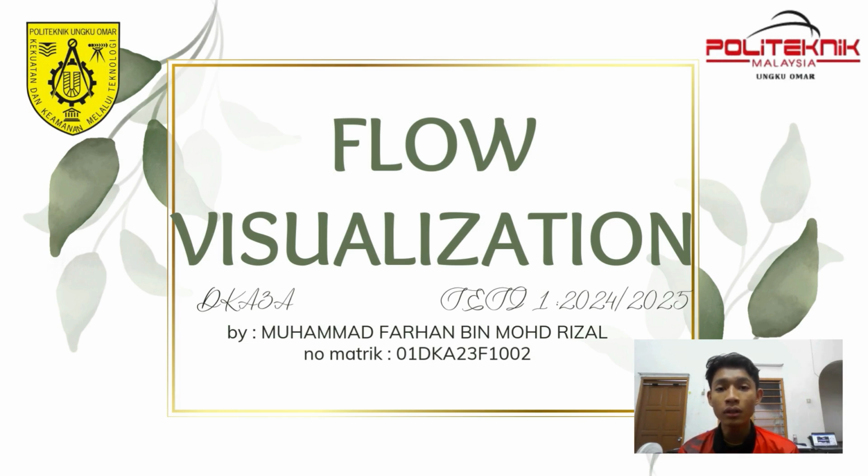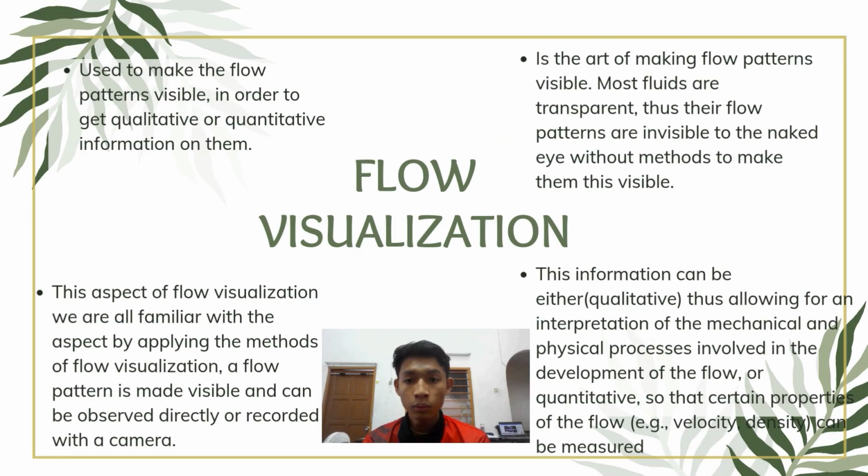Now, I will explain about flow visualization in chapter 3, hydrodynamic. Flow visualization is used to make the flow pattern visible in order to get qualitative or quantitative information on them. Flow visualization is the art of making flow patterns visible. Most fluids are transparent, thus the flow patterns are invisible to the naked eye without methods to make them visible. This aspect of flow visualization we are all familiar with. By applying the method of flow visualization, a flow pattern is made visible and can be observed directly or recorded with a camera.